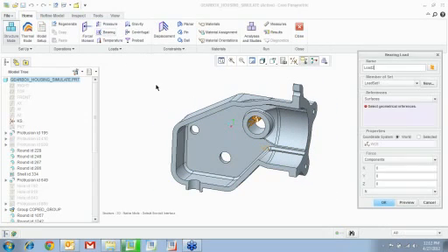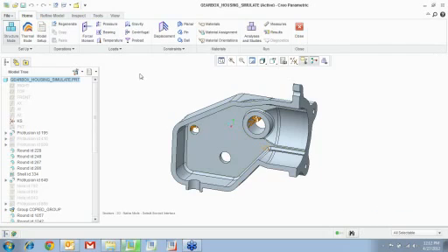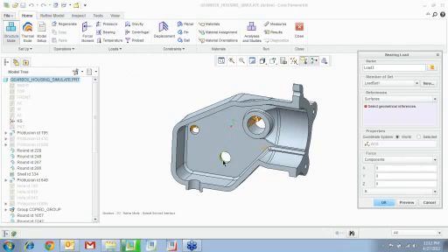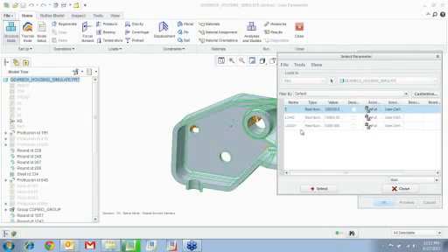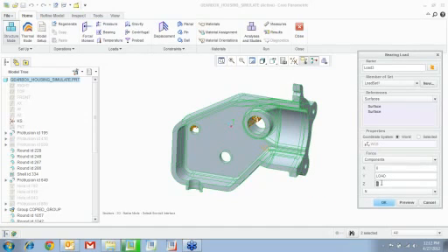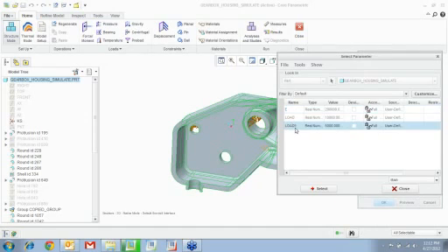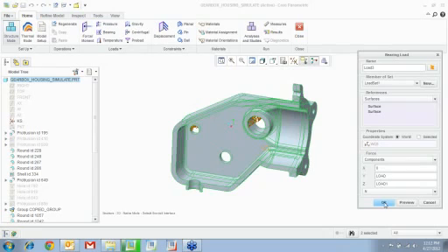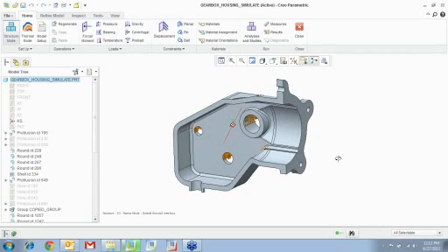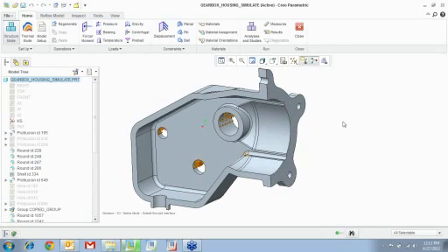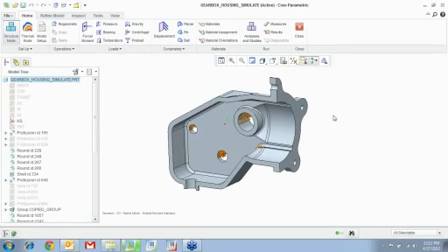Similarly, I'm going to apply more bearing loads real quick. So let me go ahead and do that. So I'm putting 1,000 here and a 500, smaller loads, and then I'm going to use the parameter load. Okay. Now, once I do that, you want to also go ahead and say constrain the surfaces.